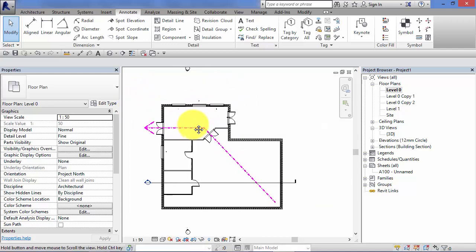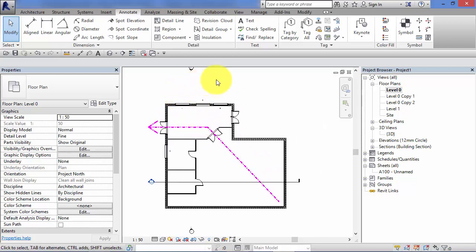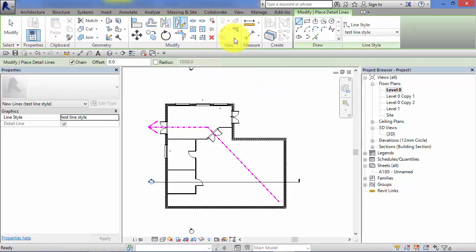So that's one use. Sort of boundaries, red lines around planning application, around site boundaries, certainly in the UK. Quite typical to put a thick sort of red line to demarcate the site. Again, you can create a custom line style for that and then use detail lines to trace around the boundary. If you've brought in a DWG of the site, a site survey, remember that pick lines tool. So annotate, detail line, just use pick lines, click on the lines of the boundary in the DWG file and get it to add those detail lines round there to show that.